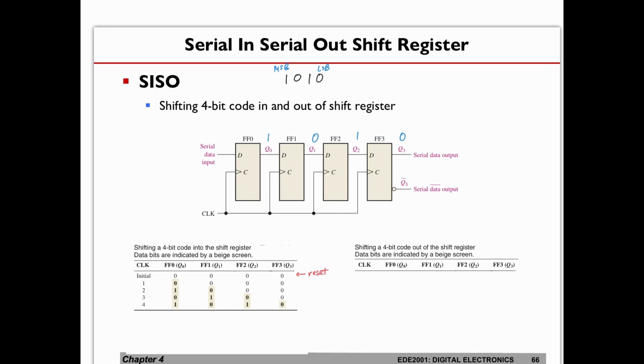So now let's continue to the shifting out of this data. So imagine I have stored 1010 using the 4 flip-flops, right? So basically we started off with storing the LSB, then the second LSB, then the second MSB, then the first MSB, in that sequence. So now I have 1010 with this as your LSB.